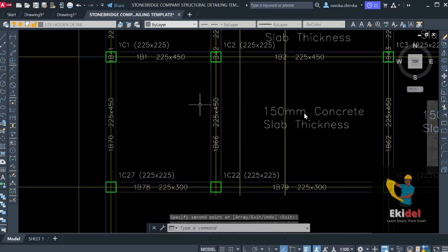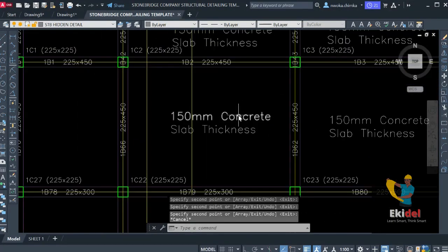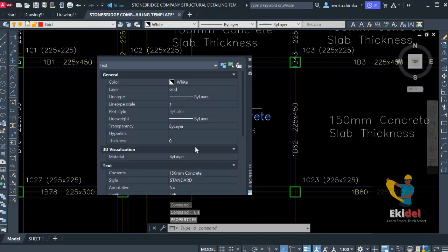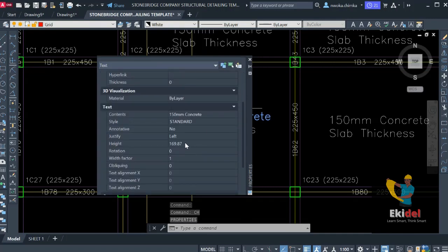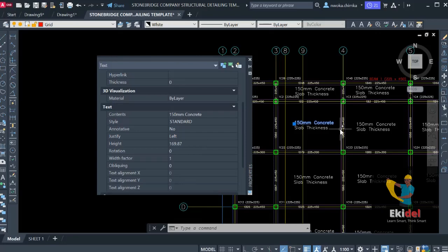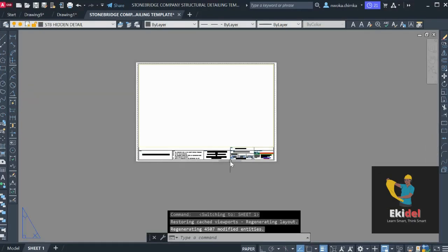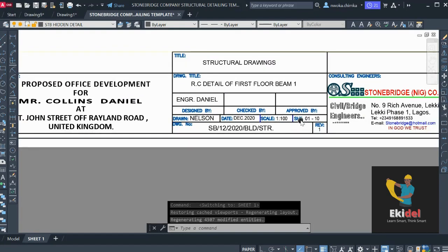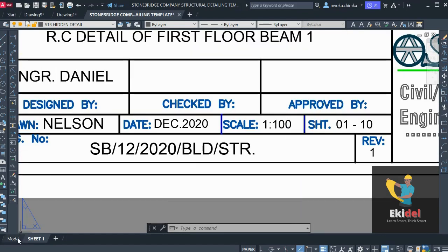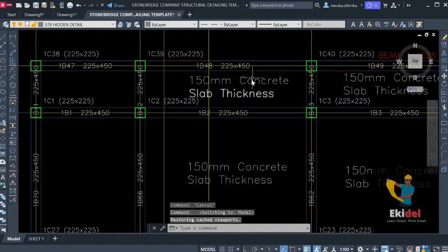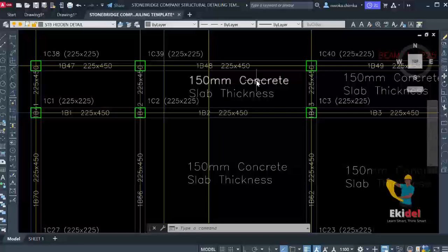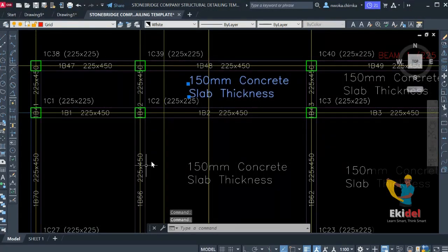And then on this place, first we have to confirm the height of this. So just click on this, right click, and say CH and enter. Then I go and create the height. This height is very big for me because of the scale that we are using. If you look at this place, I want to use a template scale of 1:100, and my text height is 1.5. So I'll just click on this.